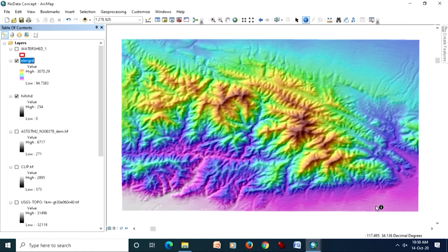It is not only giving the colors, but also giving the feeling of the terrain, or the terrain surface in that sense, or we also call it a relief map. So, very easily, without involving any classification or anything else, you can create a shaded relief model or hillside from a simple digital elevation model and display it on top of it. First is an elevation file, and then that hillside file, and give colors to the elevation file or DEM, and also 50% transparency. And once you do it, you get this kind of product.